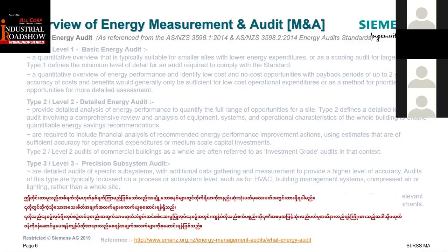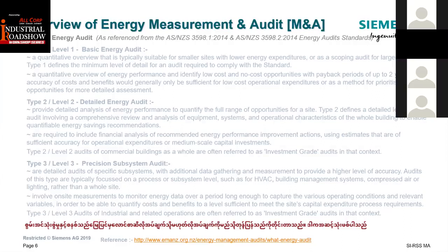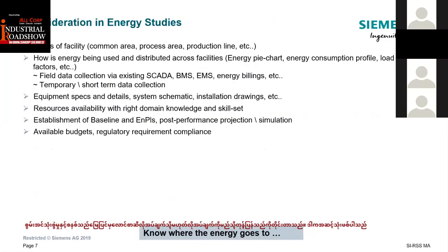All this involves measurement, and it may not be 1 day or 2 days. In some systems, you may have to deploy the instrument for at least 3 to 4 weeks. That helps us carry out more detailed data collection that enables us to understand how the system runs, not just for a day-to-day routine. During an energy audit, we also try to understand the equipment from its start to its maximum operation, or loading. At every stage, what energy is consumed and how the system responds to the demand or requirement from the field site. So that's a 3-level audit.